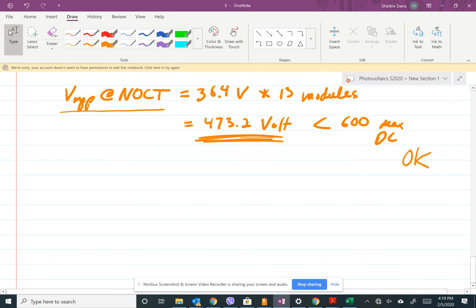Okay, so it's very, very similar to having a weak cell in series with other cells. It basically will throttle the other runs. So you have to have the same amount in each run. So if you did have to divide this up into 2 runs, then you would probably only install 12 panels with 6 panels on each string. Okay, but for us, we're good because we can keep it with 13 all in a row.